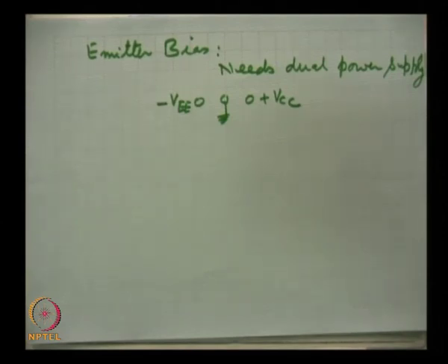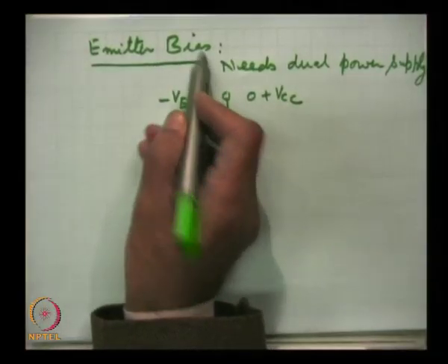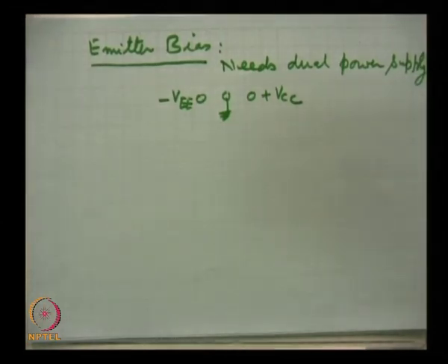circuit is simple, and actually this is a very popular biasing scheme. The operational amplifier, we will go into details later, is one of the most important developments in electronics. Today it is hard to find any circuit, analog or digital, which does not make use of operational amplifier. So, operational amplifiers are very widely used, and operational amplifiers usually make use of this biasing scheme, because it is very simple and stability is as good as the self bias case.